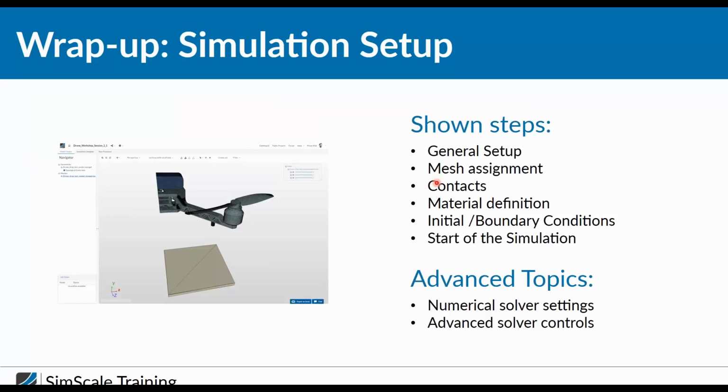So, first of all, I showed you how to set up a project, and it's quite similar to the project we did last week. So we have to create a new project, and this time we will use dynamic analysis advanced instead of static analysis. We assigned the mesh, defined contacts, physical contact as well as kinematic contacts. We defined the material, initial and boundary conditions, which describe our interaction with the environment, and finally we started the simulation.